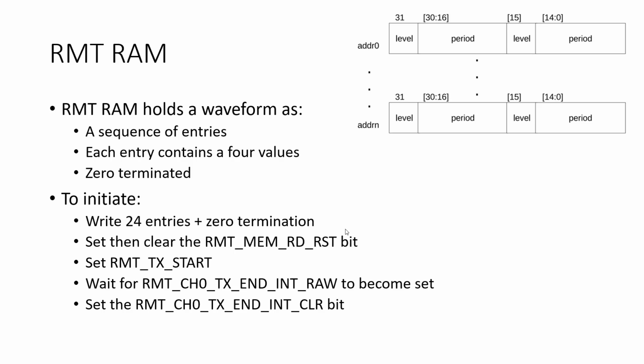So you can use this to have it wait, in case the chip is so fast that you go to program the second LED before the first one's even done yet. That register will indicate that for you. In which case you would put a busy loop in there and wait. Don't actually try and configure an interrupt. That is a huge pain to do at the hardware level. Just poll that bit.